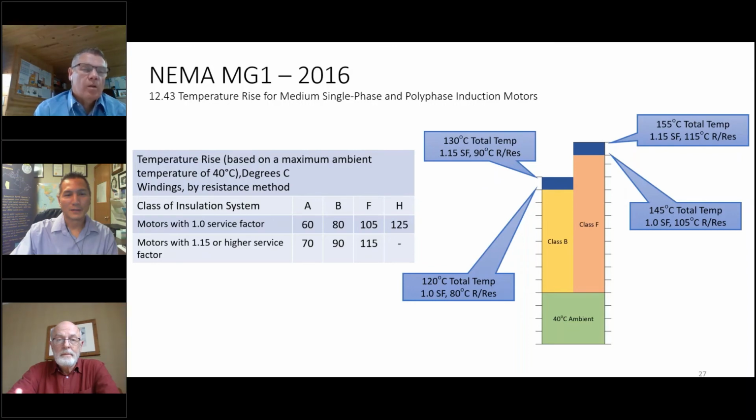Yeah, so I've spent quite a bit of my career digging into looking at root cause and what some of those failure modes might be. And it's going to be a tough question to answer right now, but one way of checking a motor, and I know it's not practical in every sense, is to see how that motor runs uncoupled. So if you uncouple the motor, disconnect it, and then take a current reading, let's just keep it real simple. Let's say we're talking about a 25 horsepower motor, and if we use my example of 575, well, that full load torque and current would be about 25 amps, give or take.